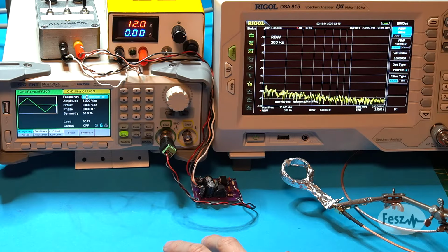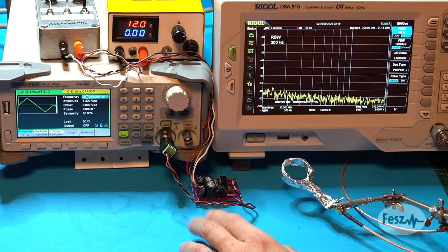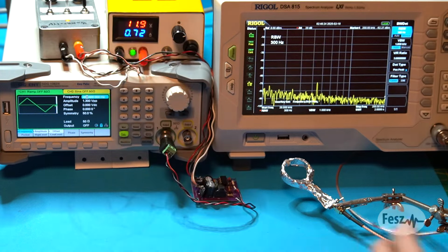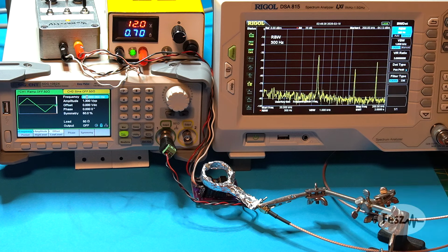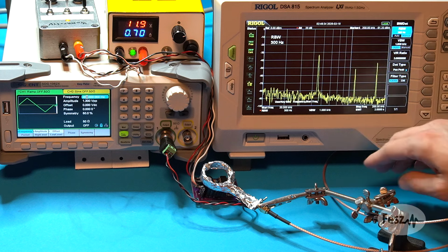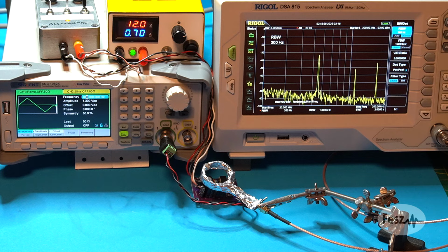To highlight this effect, I created a rather simple setup based around the boost converter we looked at previously. So when we turn this on and come close to it with a magnetic near field probe, under normal operating conditions, we can see the emissions from it are forming a clear set of peaks. In this case, the fundamental is around 55 kHz, and then we see the upper harmonics. So this is the typical emission shape of a fixed frequency converter.